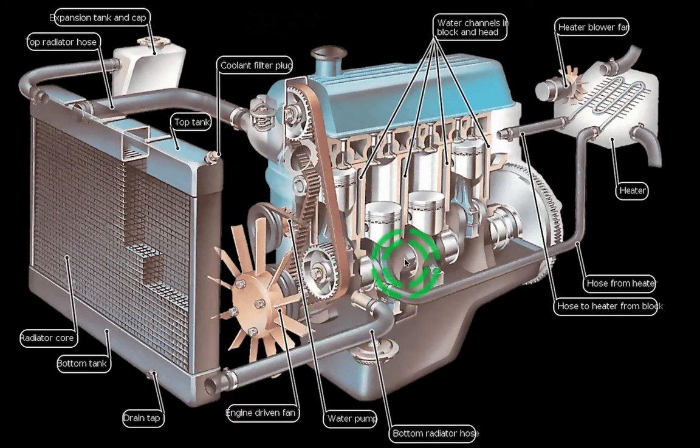Why does it do that? Because it allows the engine to warm up first. When you turn it on, it's like 30 degrees, let's say, in Dubai. So what happens when your engine is not really warm? It's not performing so good, because an engine performs best at its operating temperature, which is around 80 degrees, right? Before that, the combustion is not 100% complete.